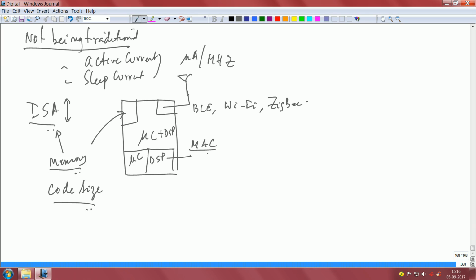If you have a very good instruction set architecture, the code that you write will be small, the code memory will become small, and if memory space decreases, then the system is a lot more energy efficient, because you are not switching on those memory cells. So everything is related: memory space, energy efficiency, code size, the instruction set architecture and so on.